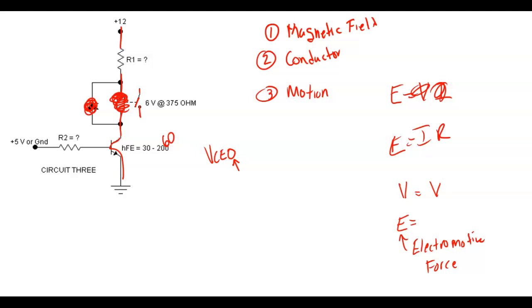That's why on PLCs, every relay running off our 24 volt outputs will have this counter EMF diode across the coil. We have suppression on AC too, but especially on relays. That's the purpose of the diode.